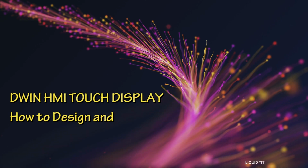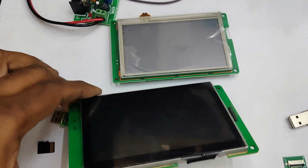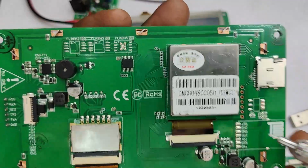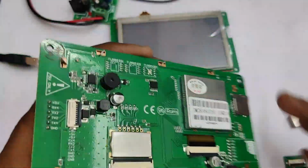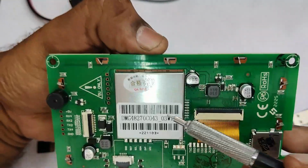Hello all, this video is on developing graphical applications on a DWIN HMI touch display and interfacing with microcontrollers like Arduino. In this video we have a 5-inch capacitive touch display. Please note on the resolution, this is 80480, which means 800 by 480 resolution, 5-inch, and the last letter represents capacitive.